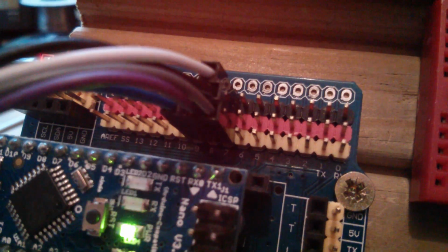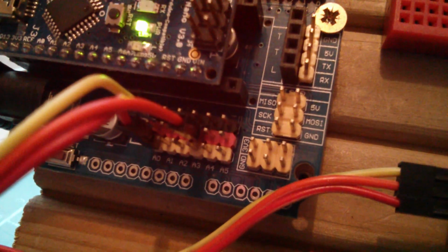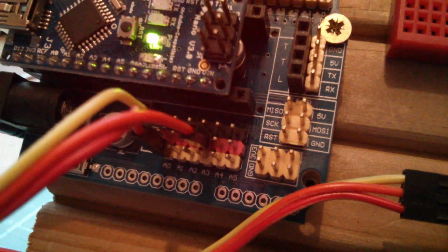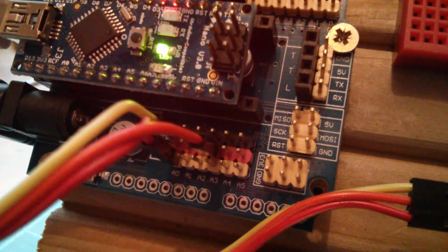Now that row of red connectors at the top there, the digital 5 volts, doesn't really matter if it's on the switch mode power supply, because digital signals have huge noise immunity. They're either 0 or 1. So that could stay connected to the switch mode power supply, and it's going to need to be for this project because I'm drawing quite a lot of power to light all my LEDs. But what I really want to do is connect those 6 VCC red connections at the bottom there, the analog ones, to the linear, the analog 5 volt regulator.